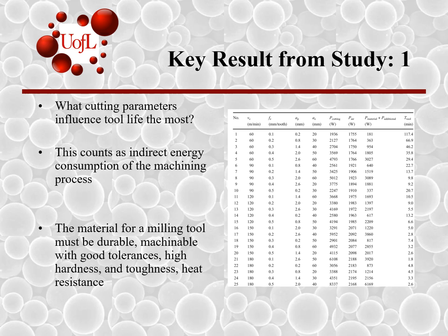The first question was what cutting parameters influence tool life the most? This is part of the indirect energy consumption of the machining process. It would be considered the tool life. So on the far right side is the tool life and how long it's lasting in minutes. And there are all the parameters, like cutting depth, cutting width, and the speed the tool is actually moving across, and it also gives the energies that are used.